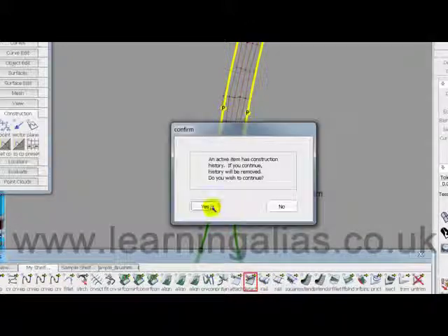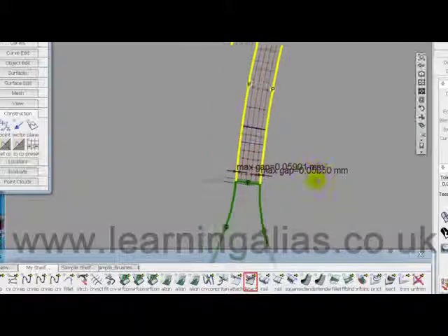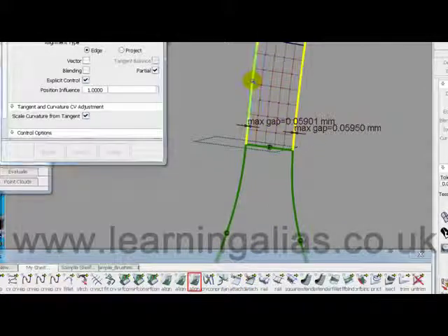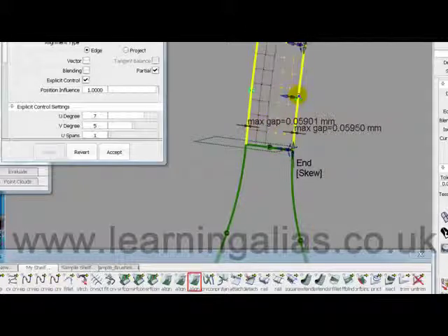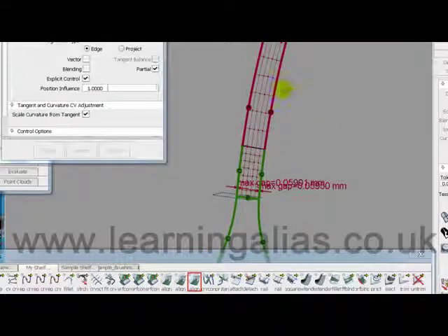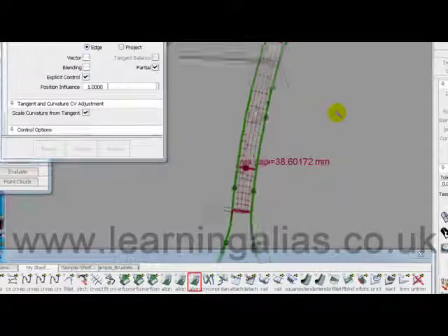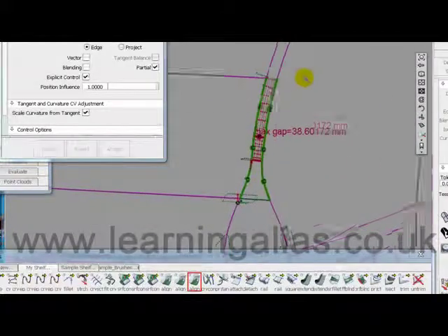and detach that surface, because I know the problem is caused by this area here, and I'm going to detach it to about there, I think, and hit go. And then I'm going to align this part here, this new surface that we've created, and you see we've got curvature there and there. So next thing to do is align this, pick nothing, E and F, and then direct model here to get curvature at the ends of your surfaces.